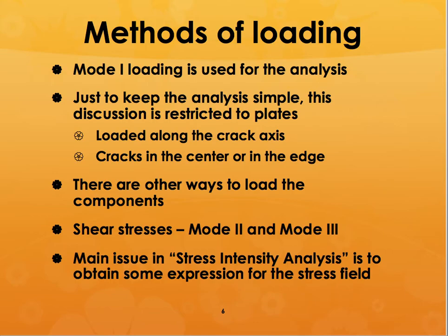And just to keep it simple, we will limit ourselves to plates, loaded along the crack axis, with the cracks in the center or at the edge. There are other ways to load the components, like shear stresses in mode 2 or mode 3, but you still use mode 1 because that gives you the lowest value of stress required to make the material fail.